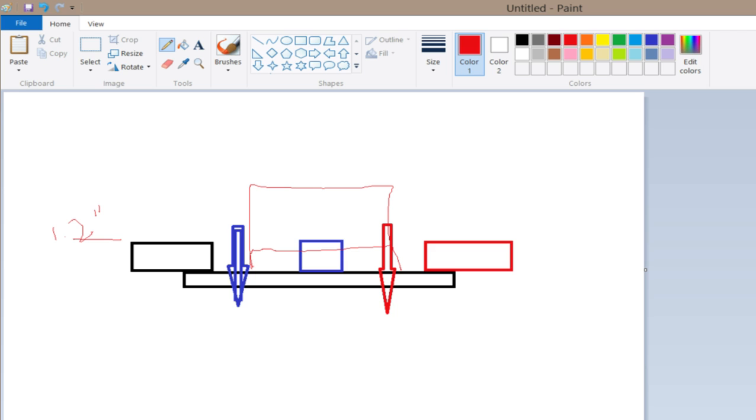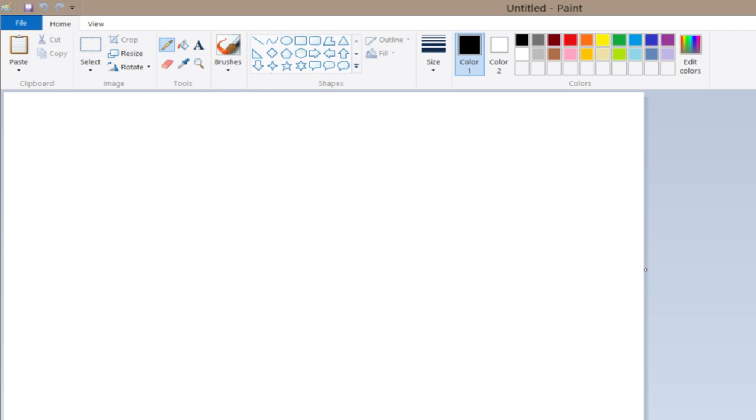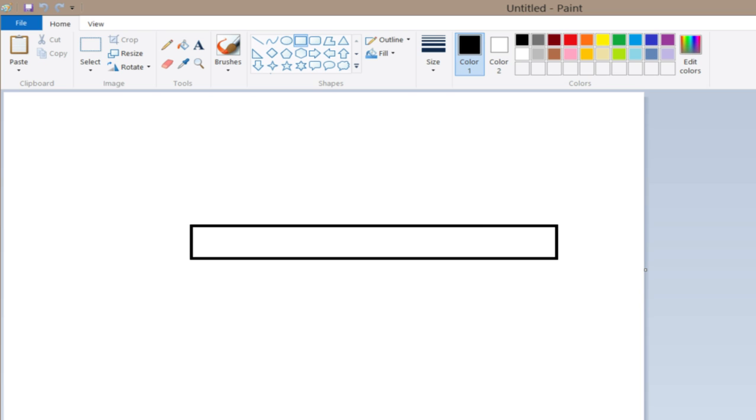Is that good? No, because if I've got my part, my drill tip is going to go right to there. And it's going to leave this little cone in the bottom, right? So what I really want to do is go to there. So I'm going to have to drill past the part. Okay?